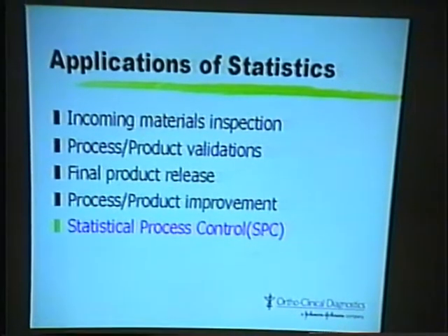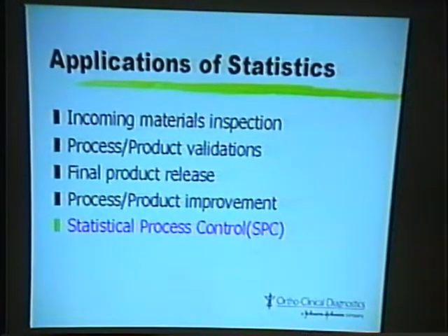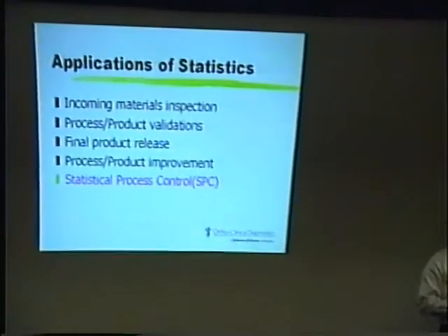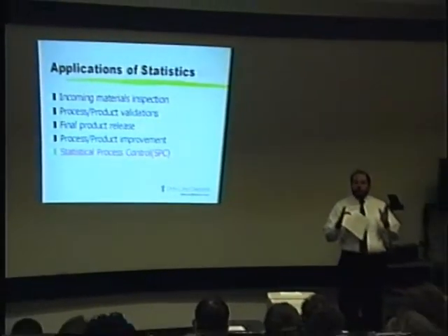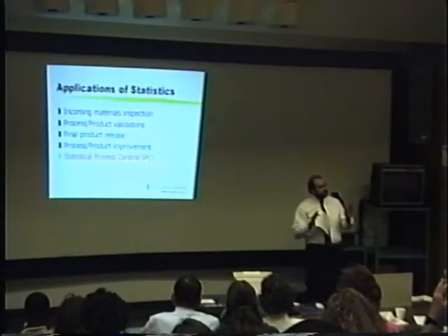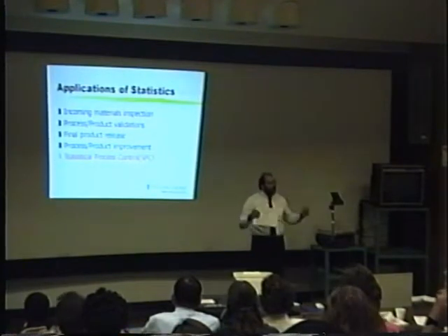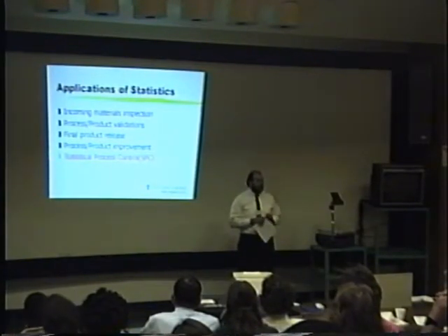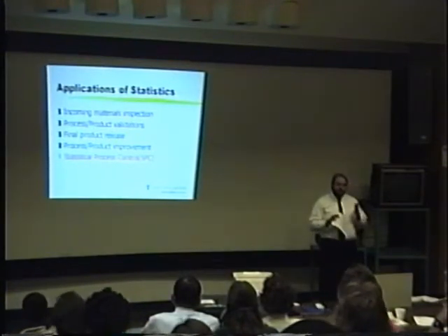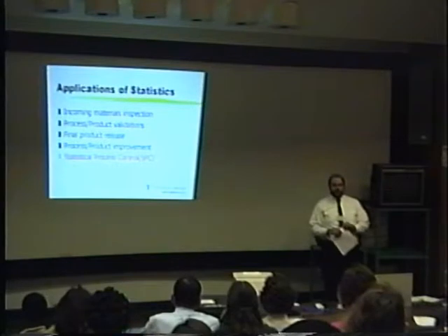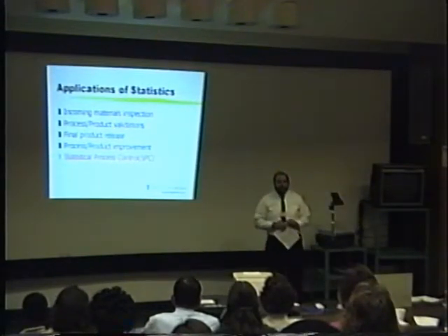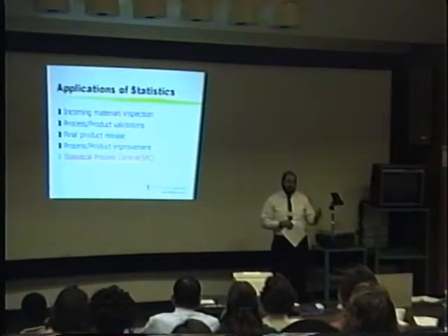Statistical process control. I'm not going to get into details of this, other than to say this is a way in which processes can be monitored. The hope is to, first of all, figure out what range you expect the process to operate within, let's say in terms of an average. Where should the average fall if everything is going well in this process, what's typical, and establish limits and use a graphical technique to understand, on a day-to-day basis or hour-by-hour basis, whether the process is continuing to operate where you expect it to be operating, and to raise a flag when it does not.